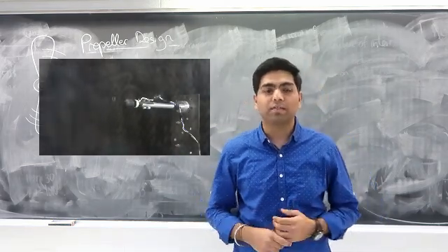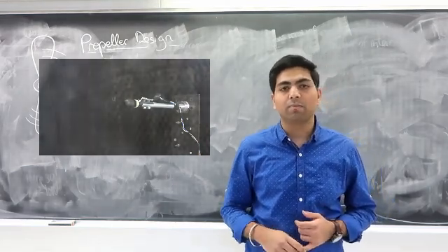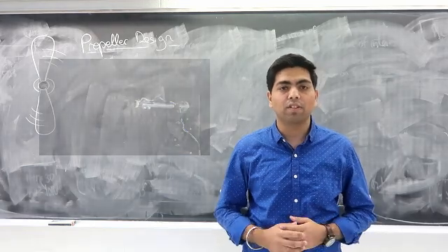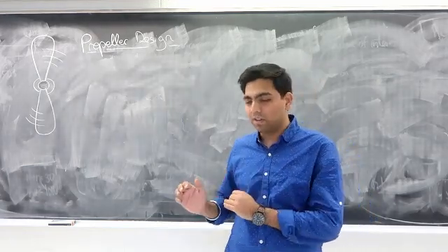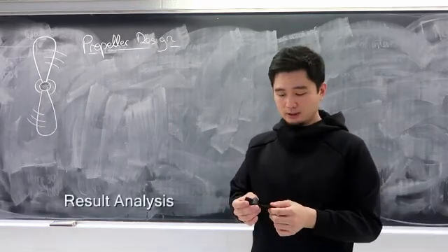And then we started giving a free stream velocity of 5 meters per second, and we changed our RPM from going from 5 to 6 to 7 to 8, 9, 10 up to 12,000 RPM. The thrust and torque were obtained and were tabulated.